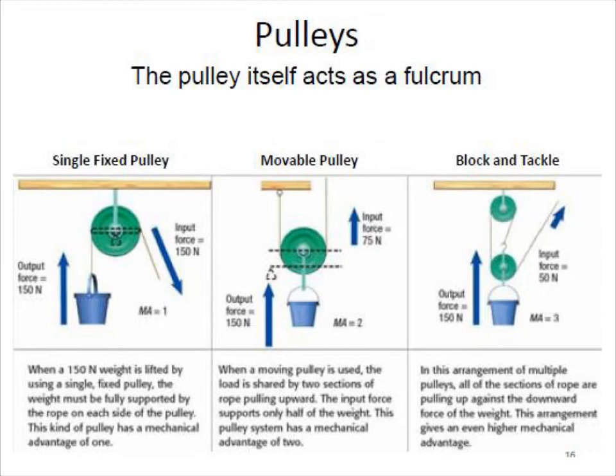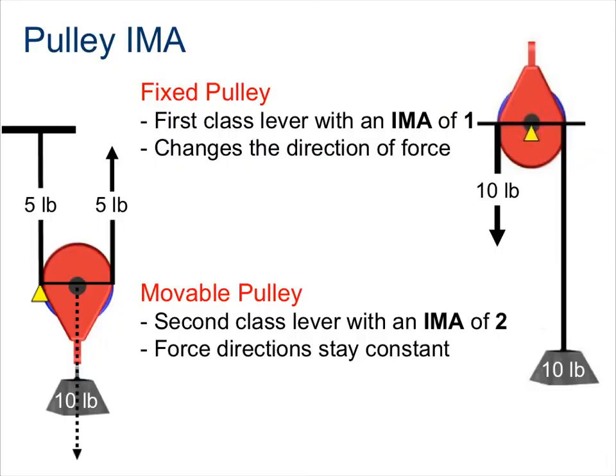This is known as a block and tackle system, designed to reduce the amount of force needed to lift a load. However, the same amount of work is necessary for the load to reach the same height as it would without any pulleys. If a pulley system reduces the magnitude of an effort force, the effort force must act through a greater distance. The IMA of a pulley is equivalent to counting the number of strands opposing the force of the load. The method for calculating IMA is only true if the strands are opposite and parallel to the resistance force.